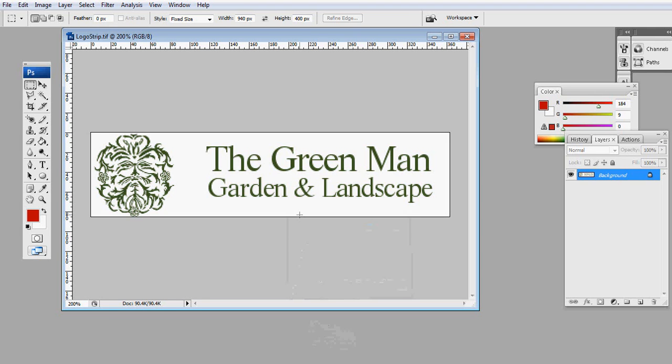You may well have a logo like this, which is taken from a website, and you can see that the logo, the image part of the logo, is very complex, and to redraw that using CAD software is going to take an inordinate amount of time. Well, the good news is you can use an image like this in your title block. Just paste the image into the title block using the mechanism that we'll show you in a moment.